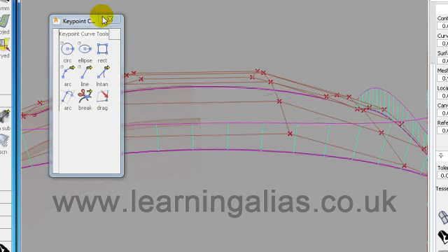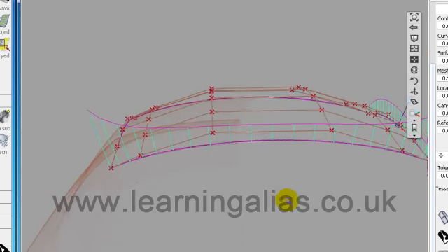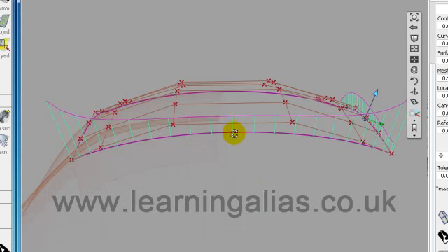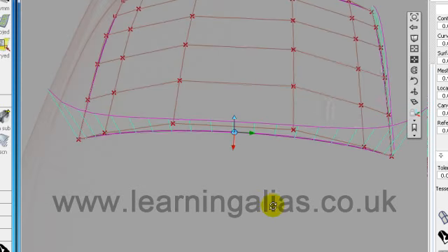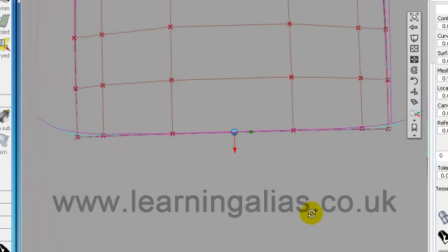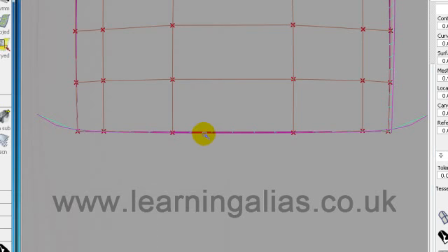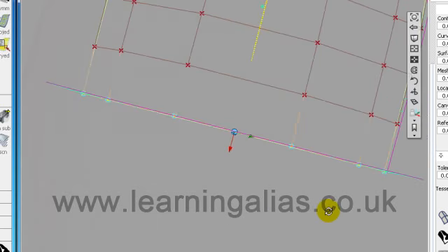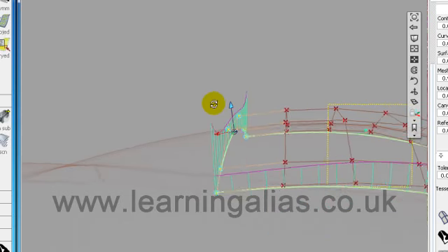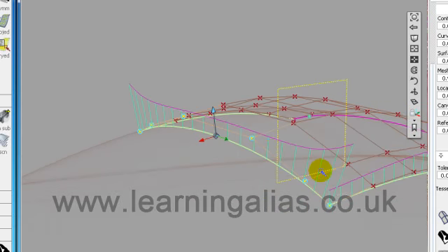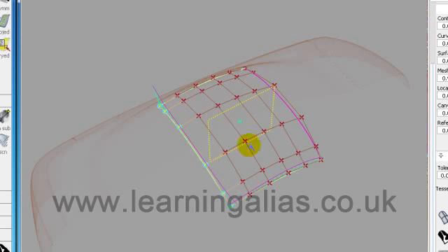We're going to planarize it between ends, so put your point of focus there and turn it so that you're looking directly down the plane that you want to achieve, and then take the Planarize Hull tool and hey presto, it's that simple. And there it is. Beautiful, isn't it? So that's how you planarize the hull, preparing it for the next stage.